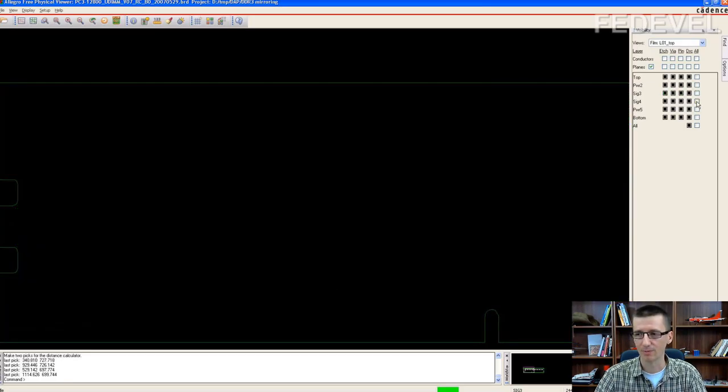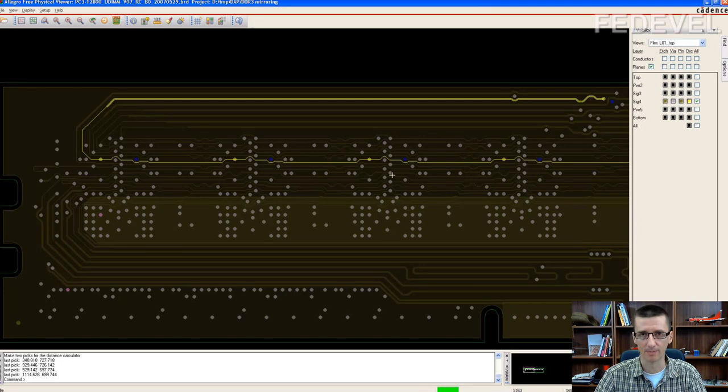What is the advantage? Do you know what the advantage of this is? You can very easily route signals between the memory chips, and you can very simply just copy and paste these parts, these segments which are here. You can copy and paste them here, use them for the connection to the other memory chip, and copy and paste it also here. See, here are some waves, here are some waves. It is exactly the same here, because these segments here, they are copied and pasted here.